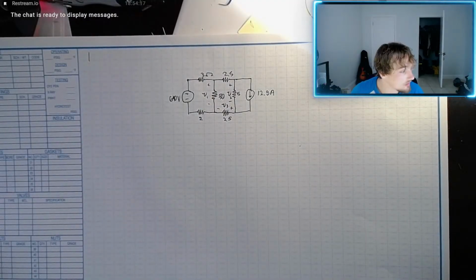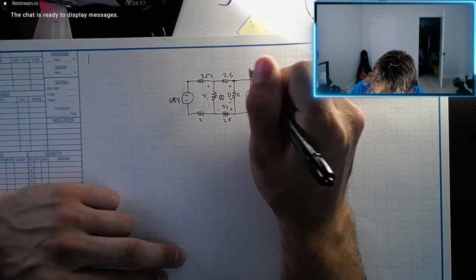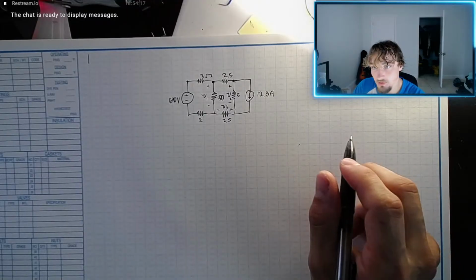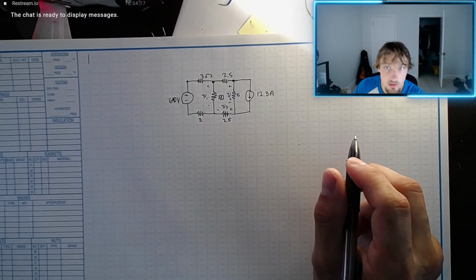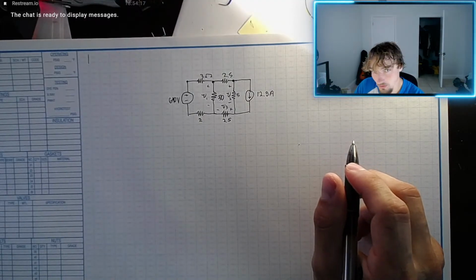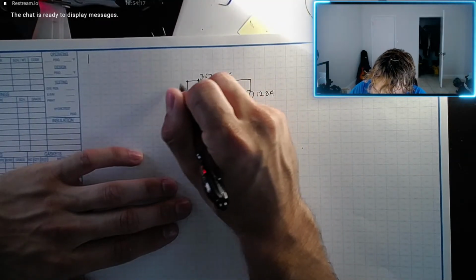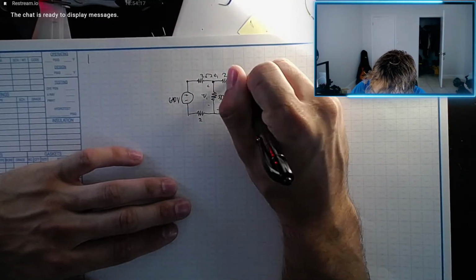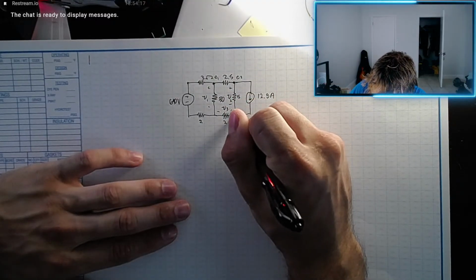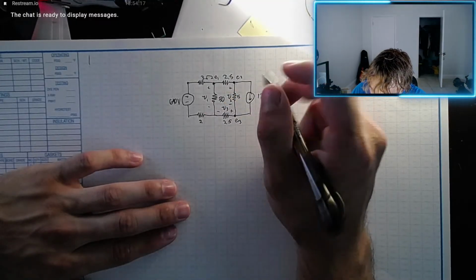Okay, now let's begin the nodal analysis. Which nodes do we not know the voltage of? Because a node is equivalent to volt. Well, no, we're going to use KCL, Kirchhoff's current law. We're going to use Ohm's law to get our node equation. All right, this node is 640 volts. We're going to call this E1, E2, and this one E3. Okay, 12.8 amps. That'll come into play, but not right now.